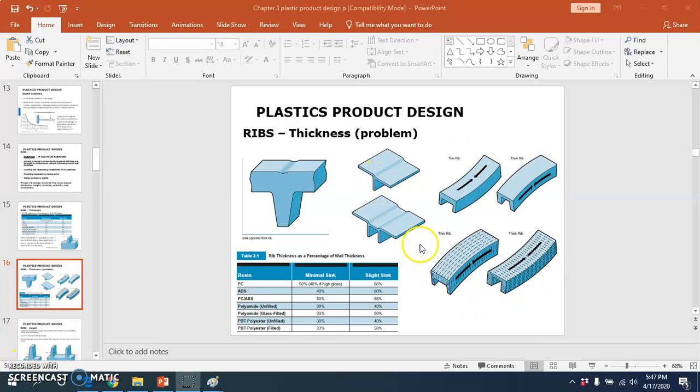This image shows how rib thickness affects warpage. Rib thickness also determines the cooling rate and degree of shrinkage in the rib, which in turn affects overall part warpage. In materials with nearly uniform shrinkage in the flow and cross-flow direction, a thinner rib tends to solidify earlier and shrink less than the base wall.